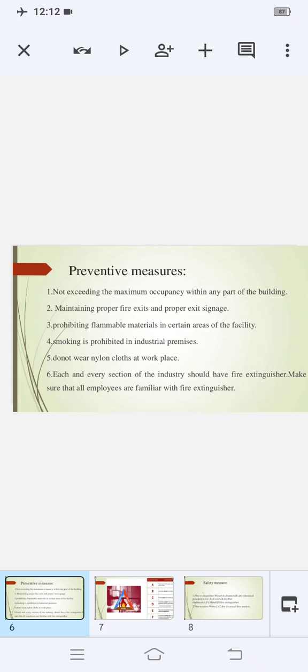In this type, the sulfuric acid is placed in one chamber and the sodium bicarbonate in another. When the fire is to be put off, the sulfuric acid chamber is broken so that a reaction takes place between sulfuric acid and sodium bicarbonate, that is an acid base reaction. Carbon dioxide is produced which exerts high pressure in the container, and water is pushed out through the discharge pipe at high pressure. As the water falls on the hot surface, it exerts a cooling effect, and the vapor displaces the oxygen from the site of burning, thus extinguishing the fire.